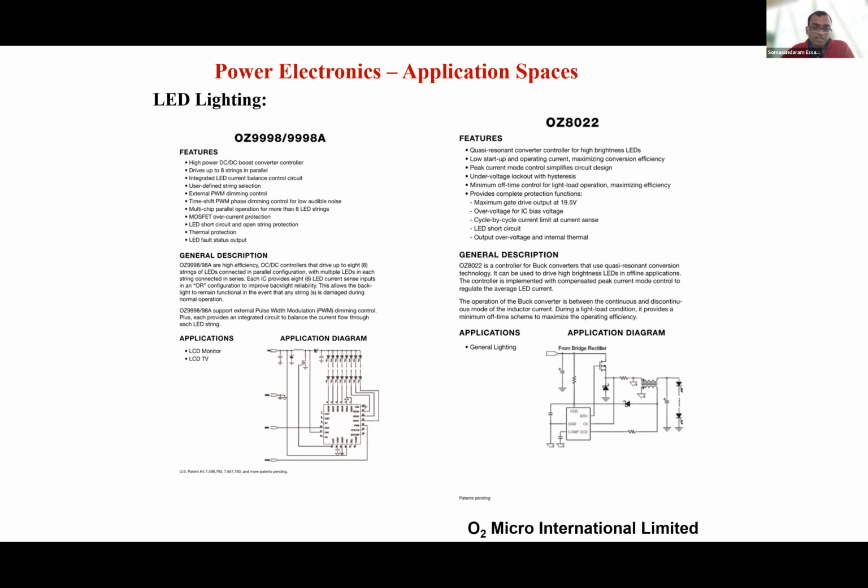In the grid that we have here, it is 60 hertz, 120 volts typically. Once that comes in, we use rectifiers to create a DC voltage, so from AC you go to DC. And then you have these converters called DC-DC boost converters to drive currents through the LED lamps, to create light.